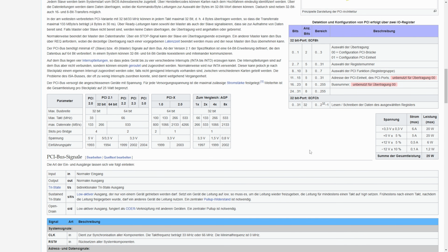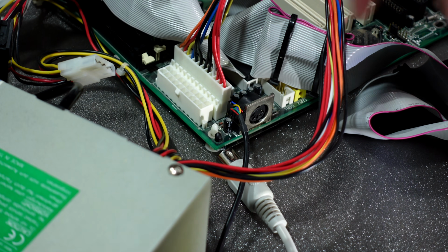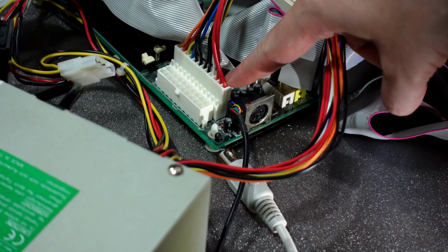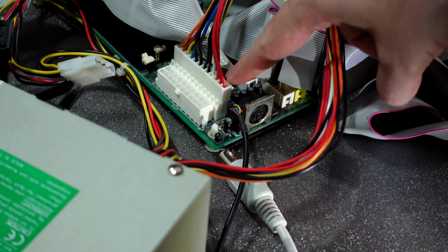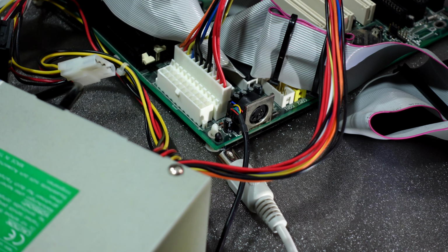While initially PCI graphics cards were driven by 5 volts, in more recent years this changed towards 3.3 volts, and this presents a problem if you want to buy a somewhat newer graphics card for an old system that does not offer these 3.3 volts. Boards that only offer 5 volts are those that have the AT form factor and can either only be powered by an AT power supply or offer connection options for both AT and ATX power supplies, such as many SuperSocket 7 or Slot 1 boards.